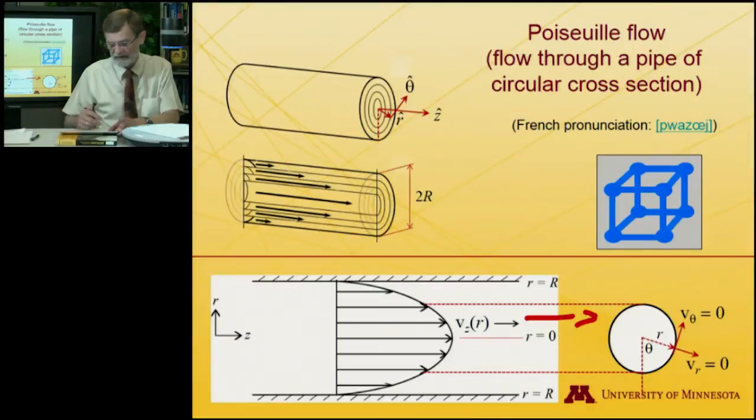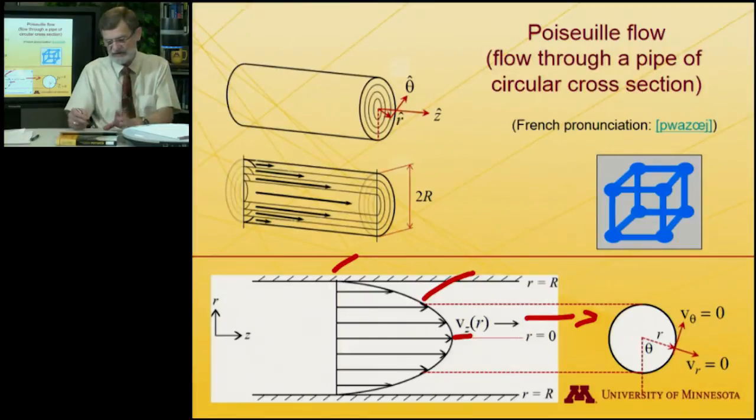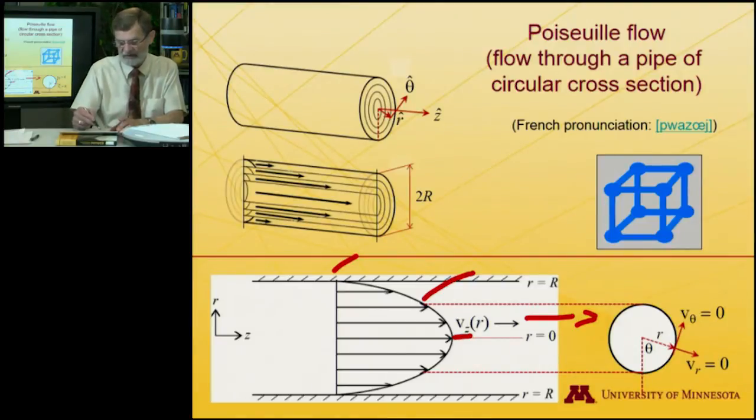And we can look at this problem just to remind you of where we're at. Okay, so here I'm back in my channel flow, or my pipe flow. I have flow coming out this pipe, and I have a velocity gradient shown here. It's maximum at the center, 0 at the edges. And now what I want to do is calculate the flux coming out. I need not just the velocity, because the velocity is a function of position, but I need the mean velocity of the fluid coming out. So I integrate that over the cross-sectional area.